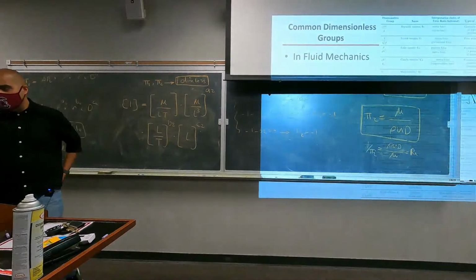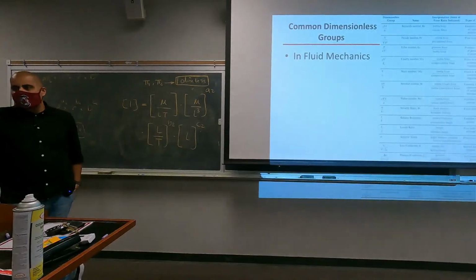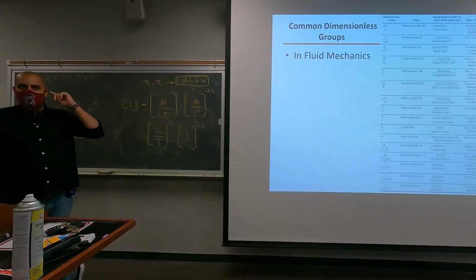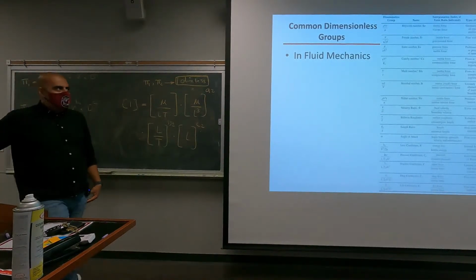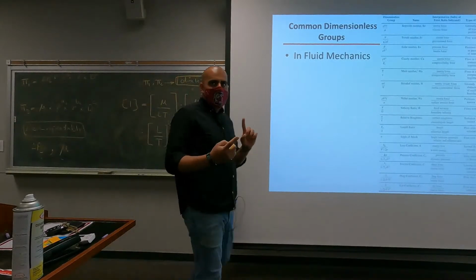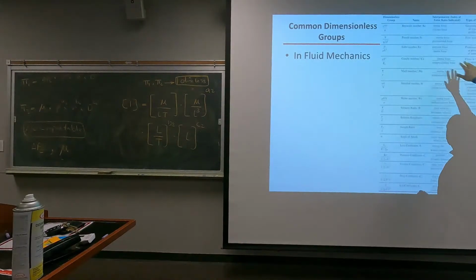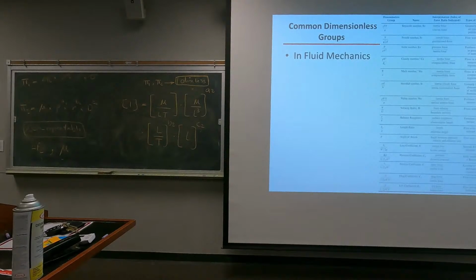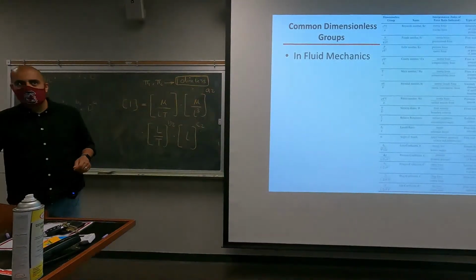These are the most prominent dimensionless parameters that you are going to see in fluid mechanics. We have seen Reynolds number a little bit in chapter 1 and 2. You have heard the name. Pretty sure we solved an example using the Reynolds number. And Reynolds number is rho v multiplied by your length scale, which can be length or diameter depending on the type of flow, divided by mu. Reynolds number essentially gives us the ratio between the inertial forces and the viscous forces, right? Which one is more dominant? Higher Reynolds number means that your inertial forces are more dominant.